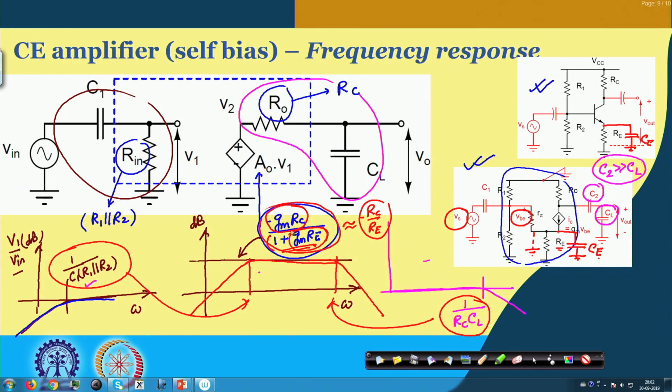That is what we said by intuition, but of course, depending on the value of CE, when we get this high gain with respect to Rc by Re, that may vary. So, depending on the value of CE and probably the effective resistance at this node, there will be some cutoff frequency, or rather I should say CE will have a direct influence on the frequency response.